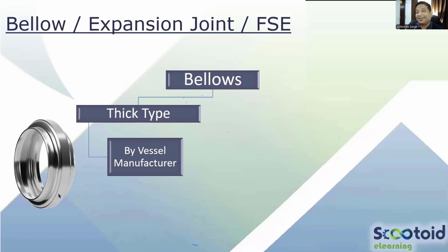It only gives some requirements, some NDE requirements. And for stresses, it's just saying to calculate stresses by doing analysis. Okay. So it does not cover the design by rule methods in Appendix 5. Okay. Make sense?